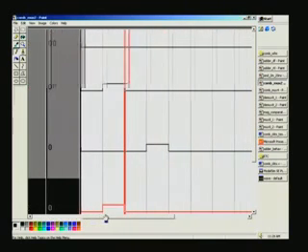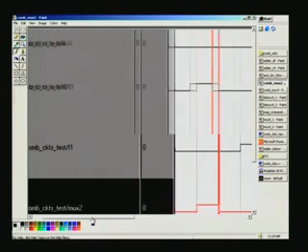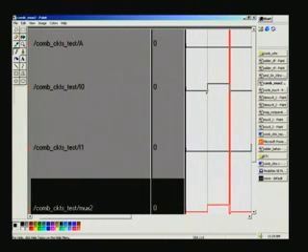And here, what you have here is I0 input as such. So this is the input that we are simulating, and through test bench we are simulating, which we have already seen here, and every 10 nanosecond we made it to 1 and then made it 0 and so on in the test bench.